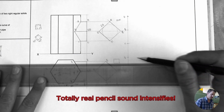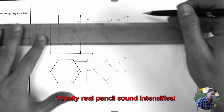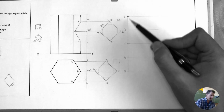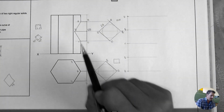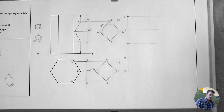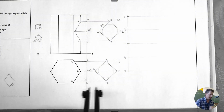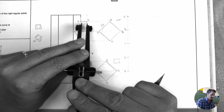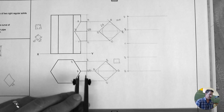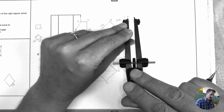So then you can start drawing construction lines out from these letters here. Remember, we are now developing the branch pipe. So once you have A, B, C, D and back to A, now we have to look at the length of the branch pipe specifically. So if I take my compass, you put it on A. Remember, every point is going to be measured from the base here. So A onto point A where it connects, and that's going to be this distance that you have on the top view, right? It should be the same.